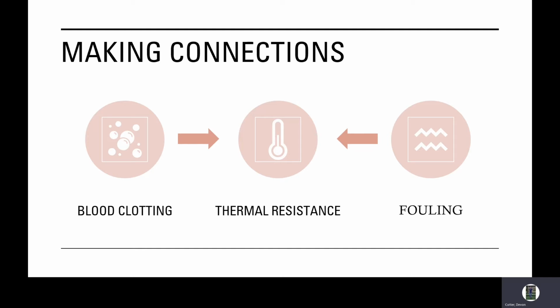a heat exchange-like concept. Vessel vein blood circulation can be likened to a counterflow heat exchanger, whereas a network of blood vessels, arteries, and veins may be viewed as a convective flow of blood parallel to a thick-walled pipe, such that the tissue, fat, and muscle represent insulation. The blood capillaries themselves represent the pipe, and the blood clotting represents fouling effects. When combining these connections, the principal heat transfer concept of interest is thermoresistance.